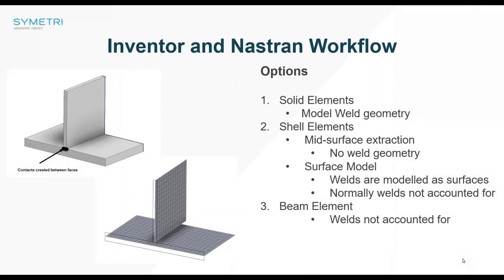This is something which we had done in the welded seminar or webinar, where we were basically looking at fabricated examples. Typically, I've seen many customers using fabrications or thin structures and still meshing them using solids. If that's the case, then we will get contacts between two solid plates. The contact is going to be highlighted by this black line. We're not going to get contacts on the edges. It's primarily going to be automatically created between the plates.